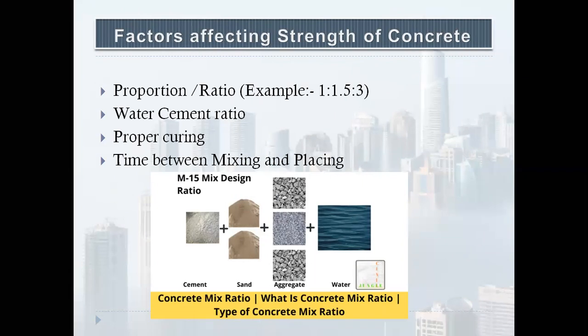It has some sort of cracks on the surface of the concrete and it is not going to develop its full stresses, right? So proper curing is important. And last is timing between mixing and placing.